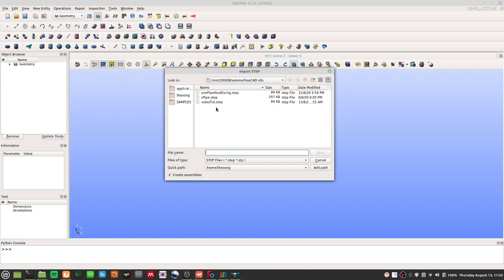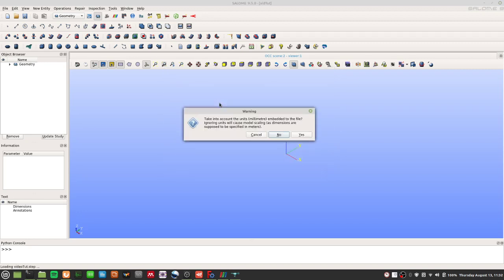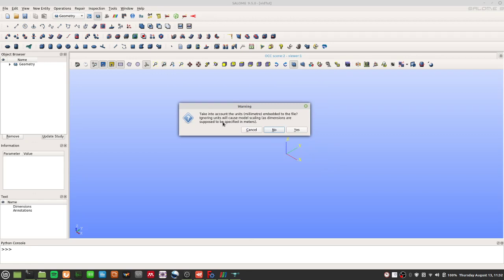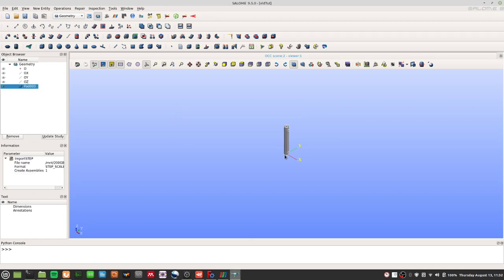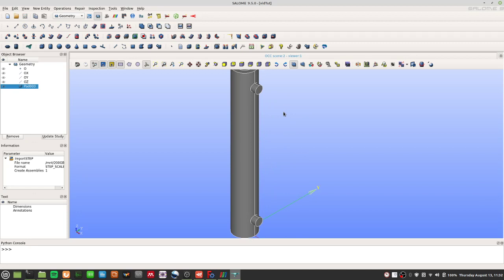Same as what you should know already when you're doing even the single region case like pimpleFoam, where you have only one region you have to deal with. Same idea. So I'm just going to do this video tutorial thing, and Salome, at least Salome 9.5, gives you the option to take into account the units of millimeter, which I don't want. I want to do this step in OpenFoam, the conversion from meter to millimeter.